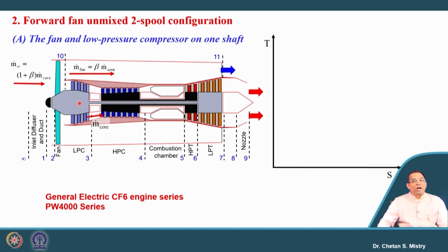So, very first after fan, what compressor stages we have, people they are defining that as say LP compressor, sometimes they used to say booster compressor, and these compressors they are different from the next stage compressors. These compressors are say our HP compressor. In between these compressor stages, we are having the diffuser that will diffuse the flow and will try to maintain the total pressure to be constant at the entry of the HP compressor.